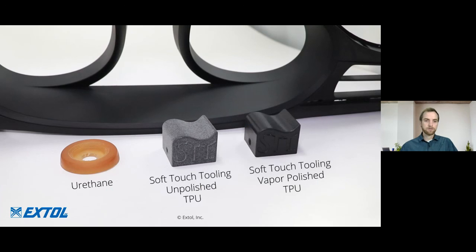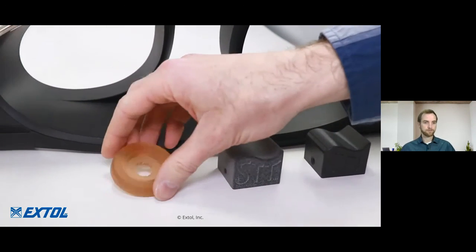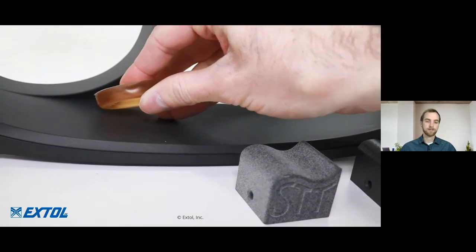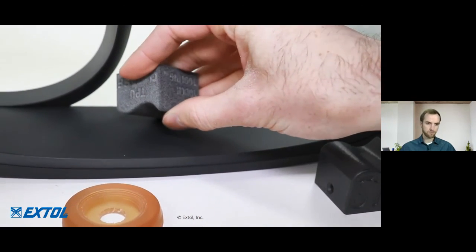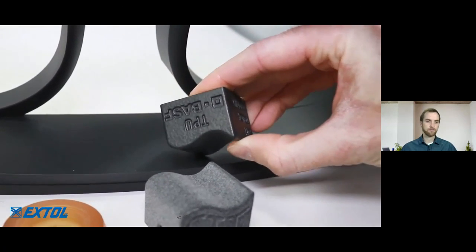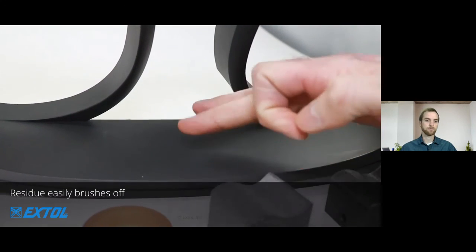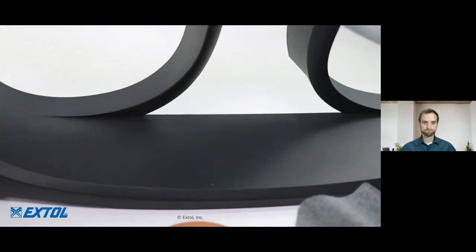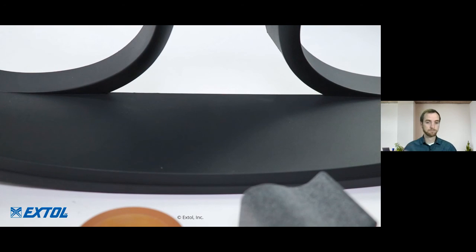And then painted glossy worked real well, had some smudging with the unpolished. So this next video is a video of the matte painted part being tested, and let's take a look at what is referred to as smudging. First, we're going to rub the urethane across the matte paint, and you can see a trail or a mark basically where that was dragged across there. The unfinished TPU a little bit more, and then the vapor polished TPU less. And with each of those smudges, they were able to be rubbed off, not permanently marking the part.